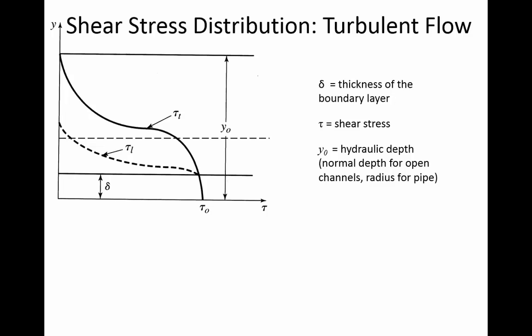So at a certain distance from the edge of the pipe, if you've got fast-moving water, then there's a lot of shear stress there. If you've got slow-moving water, then there's less shear stress. And so the magnitude of the shear stress is sort of reaching out into the flow. The faster the water is moving, the influence of the pipe edges' resistance is felt deeper into the flow